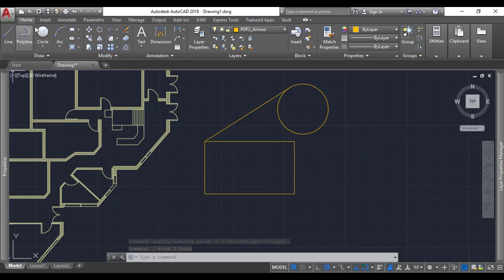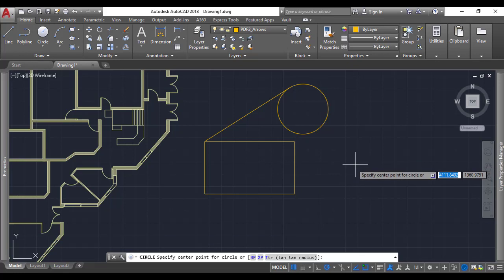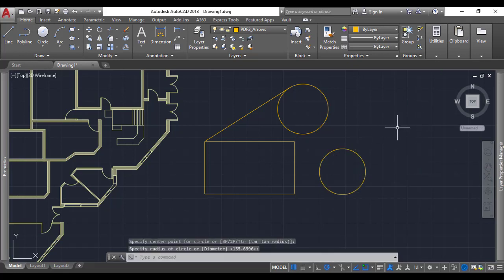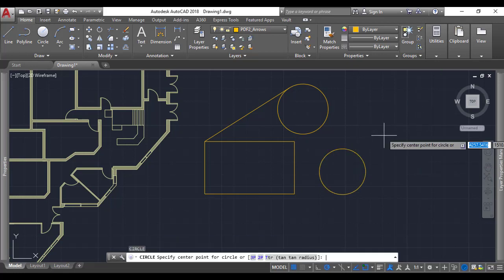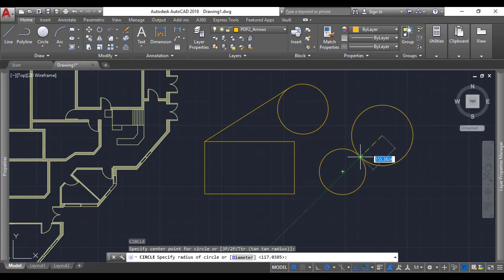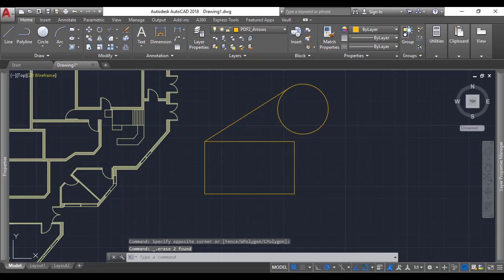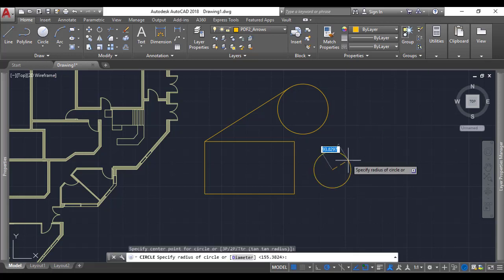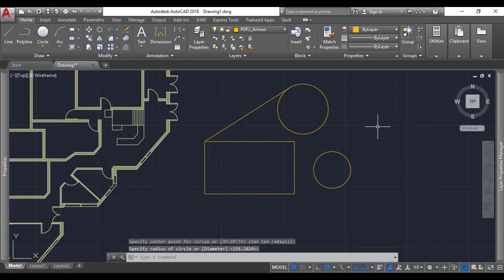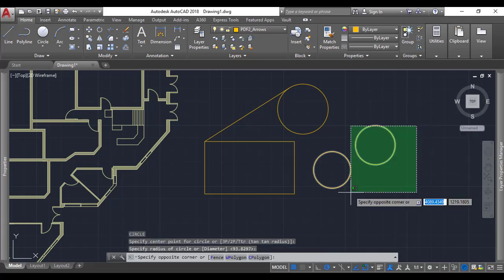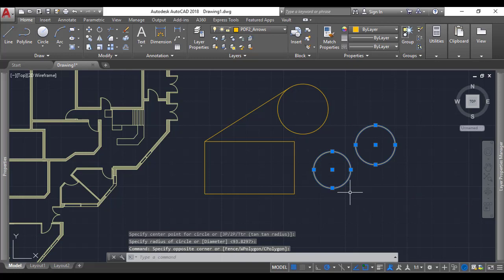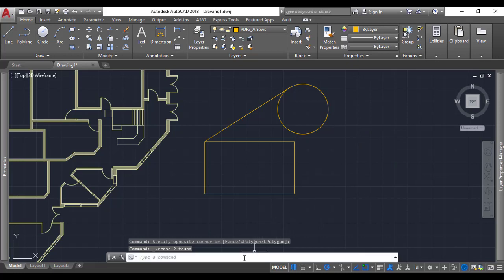What you also can do is, when you're in a command, maybe a circle, you've selected it, you've drawn your circle and it's out of the command, then you can select enter again, and it will go to your previous command. So if I've drawn a circle and I want to go back to that command, I can press enter, and you can create another circle. It works with lines, fillets, chamfers, and so forth. Now, if you just want to run it in a loop continuously, you can use the command multiple.